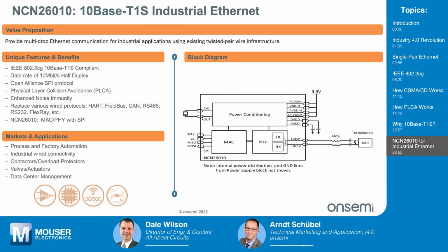We're running a predefined protocol defined by the Open Alliance. That's coming from in-vehicle networking, but they've put some effort into providing a specification for an SPI protocol that does the trick here. So we basically adopted that, and we realized that 10BASE-T1S will have a second life in automotive, so it makes a lot of sense to take on that protocol.